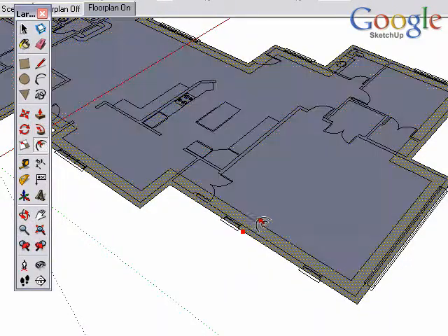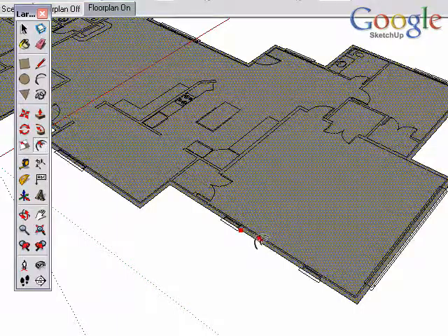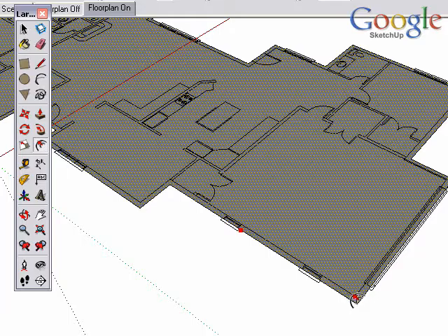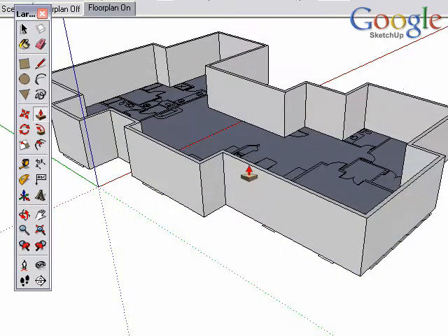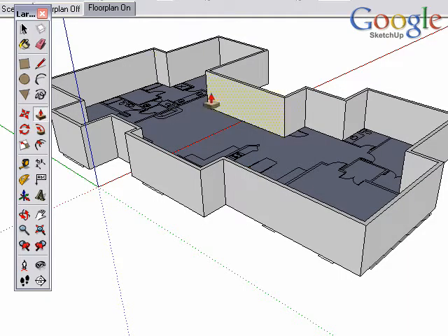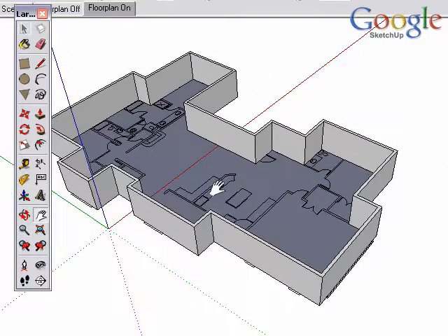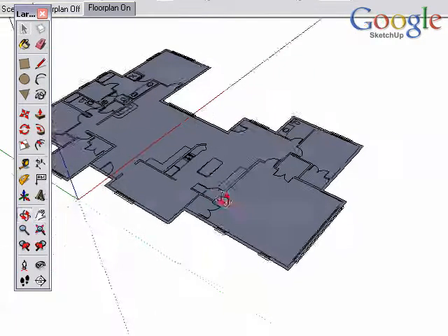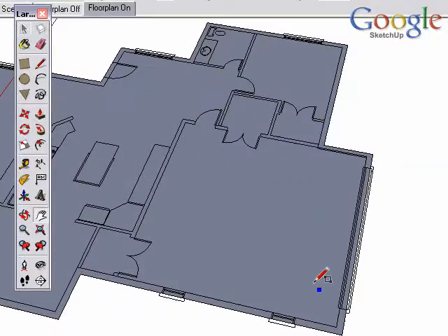walls as well, use the offset tool, offset that plan exterior, and use the CAD plan again as a reference. So now we've offset the walls in, and we can pull the exterior walls up and start working on the interior walls. Two things to consider is that you could take and group the model that we have so far so that your exterior walls will be separate from your interior walls. We're going to take this and build it as though our exterior and interior walls are all going to be one. But of course you could do it either way.